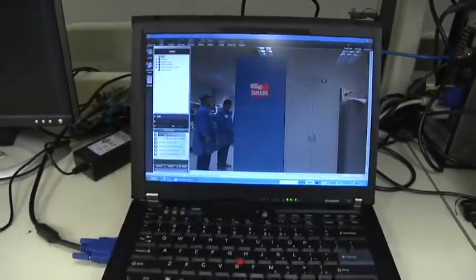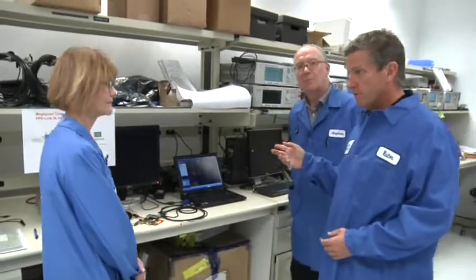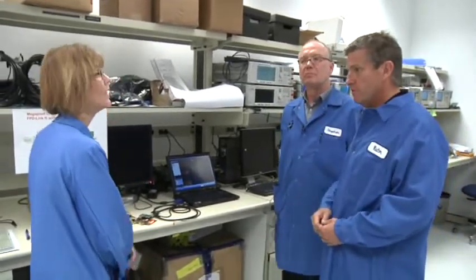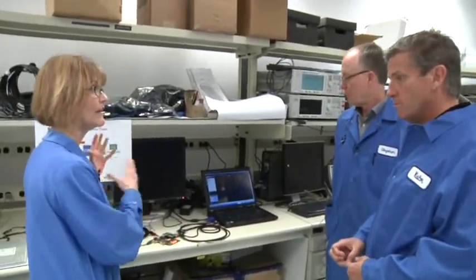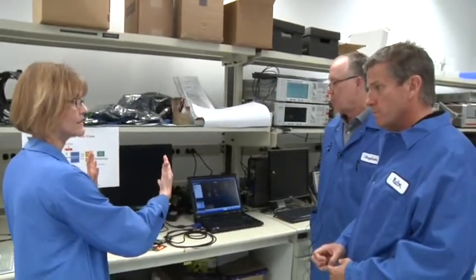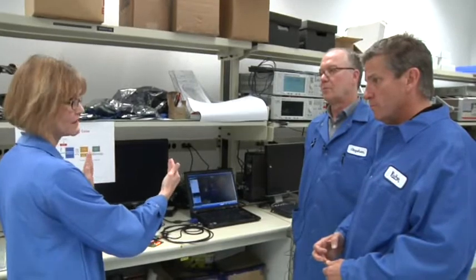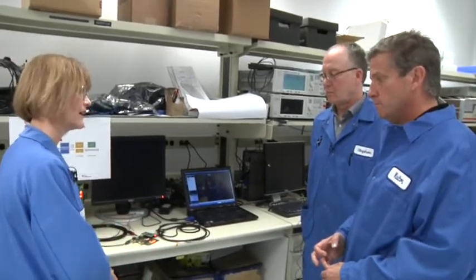And the faster you go, the more that will contribute to higher resolution? Yeah, exactly. So, right, the higher resolution requires a higher, what they call the pixel clock, the clock that's delivering the video data. And then all that information is serialized and transmitted, so all the bits of data you're sending are sent during 1 pixel clock time frame. So the faster the pixel clock, the faster this whole serial link is running.